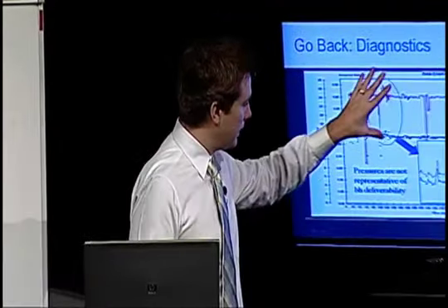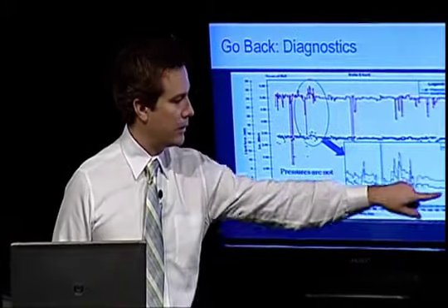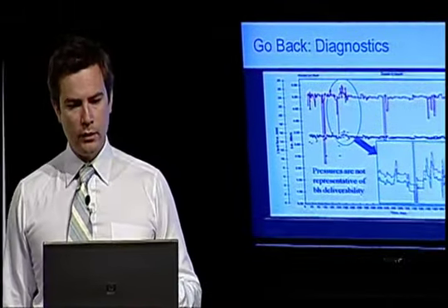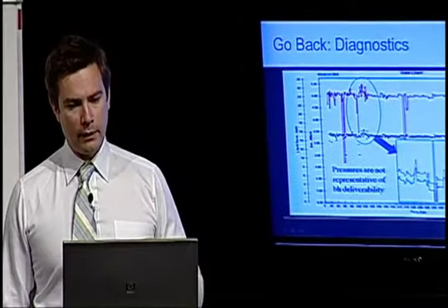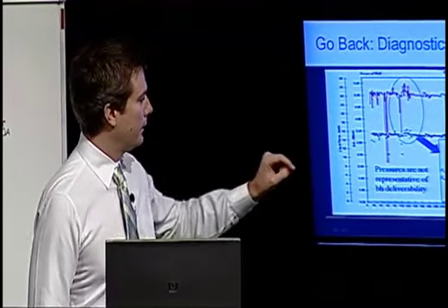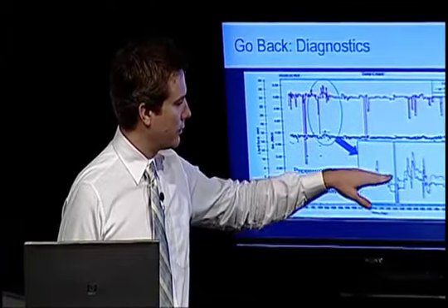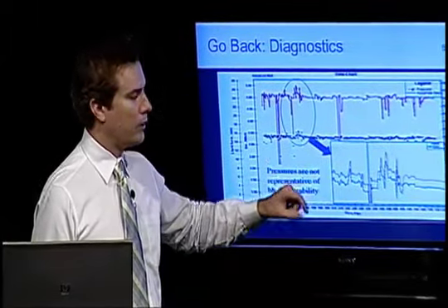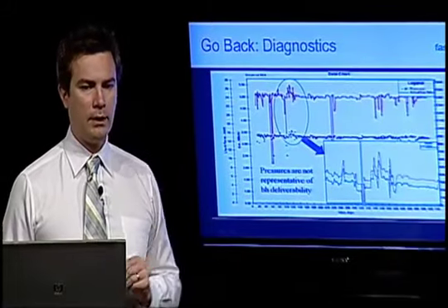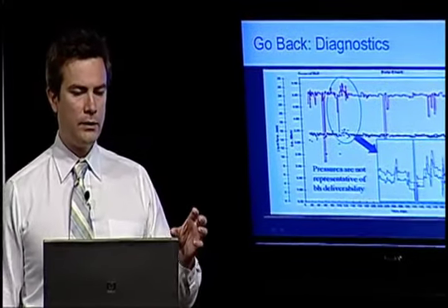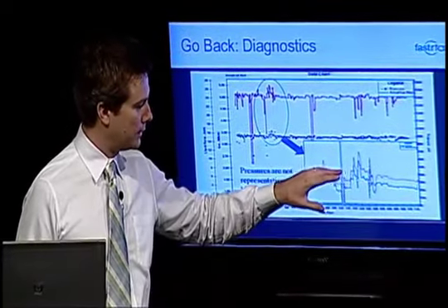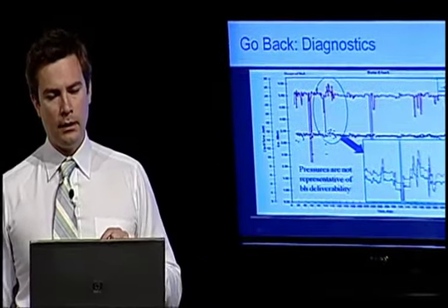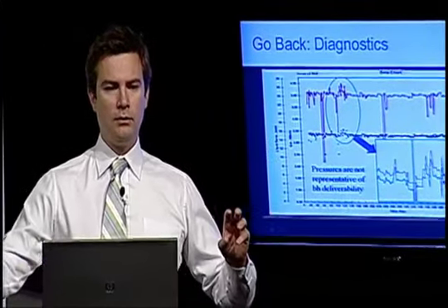So when I zoomed into this little area of the data, this is the picture that I got. And I immediately knew that there was something wrong with the data because I'm getting the wrong direction with my pressures. What I found out afterwards is that the rates are measured correctly, but the flowing pressures were measured on the downstream side of a choke that was on the wellhead. So if you think about it, if your wellhead is choked, and you're getting pressure measurements on the downstream side, these pressure measurements were actually the static pressures in a meter run. They are not in any way connected to the bottom hole.